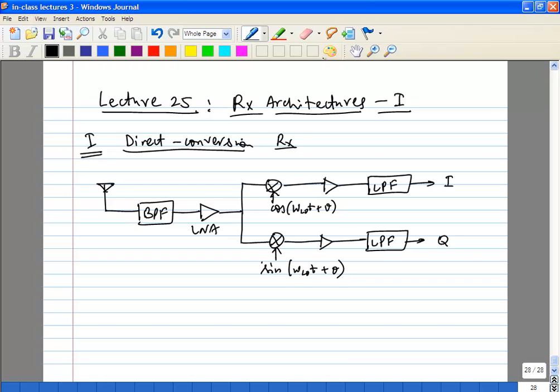The output is the I and the Q. Okay, so let's just name the outputs. In this case, when we are doing direct conversion, does the PLL not step in? Of course you do. What generates sin omega LO t and cos omega LO t is the PLL.